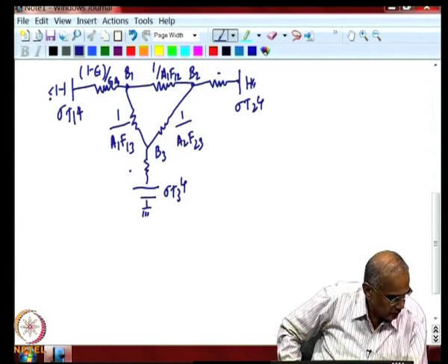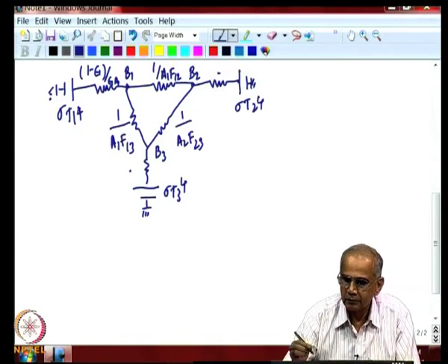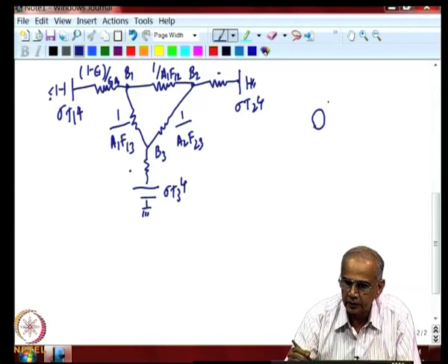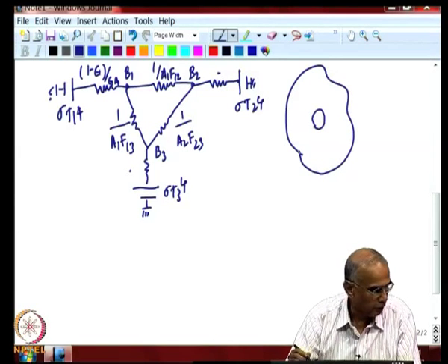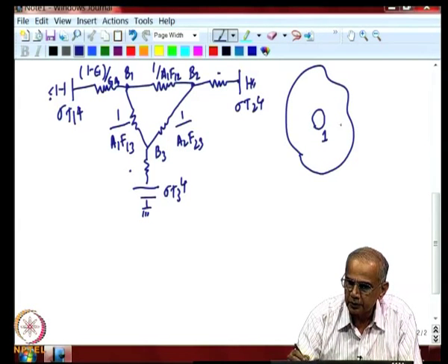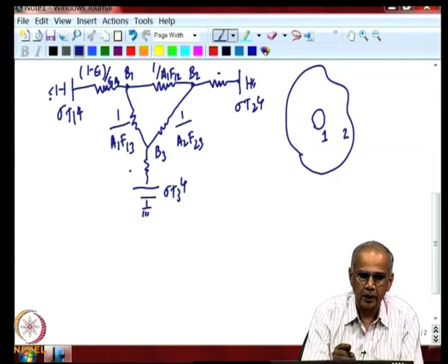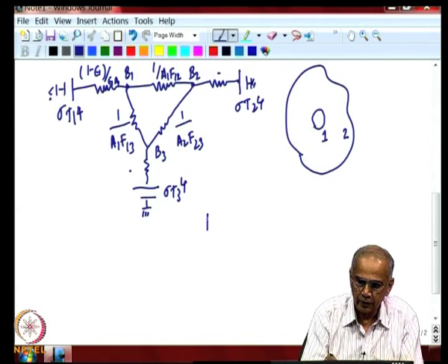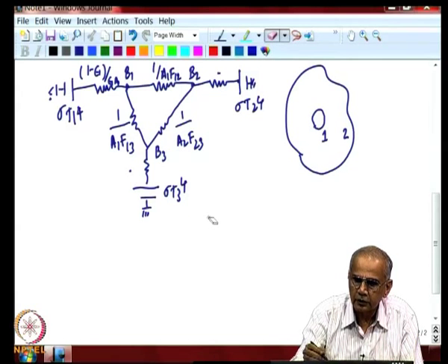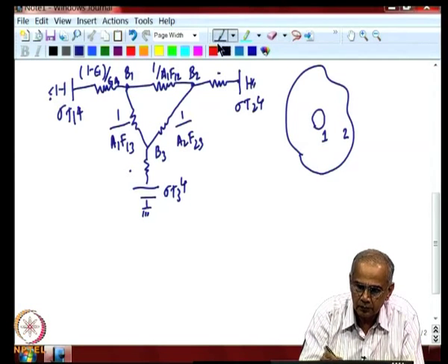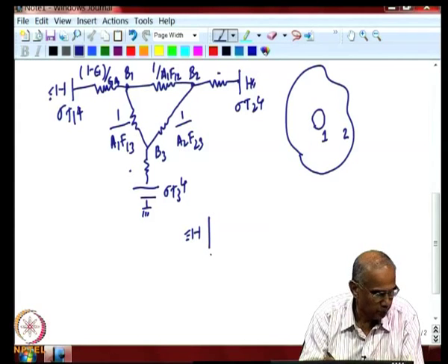Now, we also applied this for a few simple examples, and so I will illustrate one example which is of great relevance to many situations in engineering. Imagine a convex object, a cylinder surrounded by a general object. This is surface 1 and this is surface 2. So, there are only 2 surfaces, we can neglect this part. So, then we can draw our electrical circuit for this case as one battery here, this inner one sigma T1 to the power of 4.